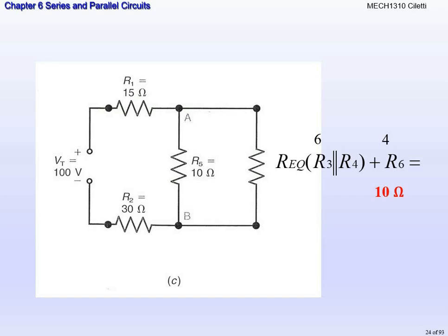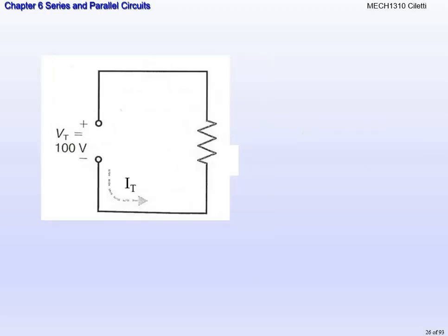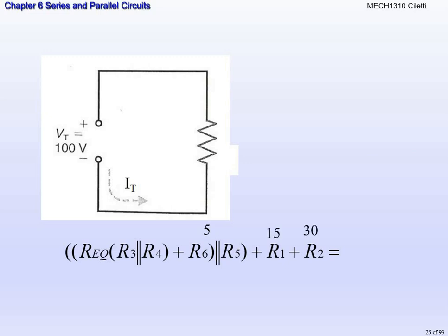So we're going to find the parallel resistance, and then we're going to redraw the circuit. So we have 10 in parallel with 10, okay? And we get 5 ohms. So that resistor we just calculated and simplified down, between terminal A and B, is 5 ohms. Now what's the relationship? We have R1 in series with that whole combination piece that we just did, that's 5 ohms, and that's in series with the 30 ohm resistor. So now we can just take 15 plus 5 plus 30 and write it as one resistor and get 50 ohms. So that total equivalent resistance right there is 50 ohms.